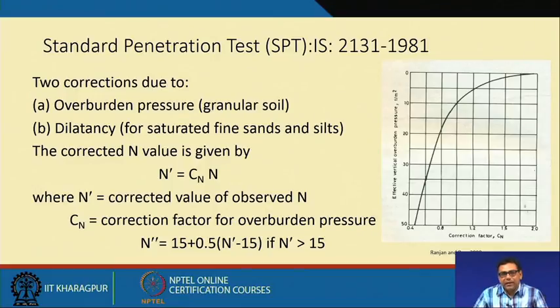If we apply shearing and the volume of the soil decreases, then the pore water pressure will increase. The opposite trend happens if the volume increases.